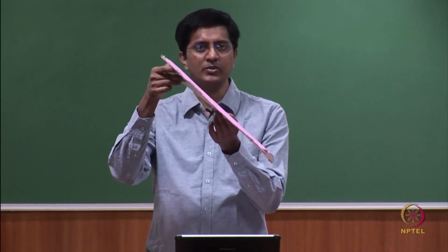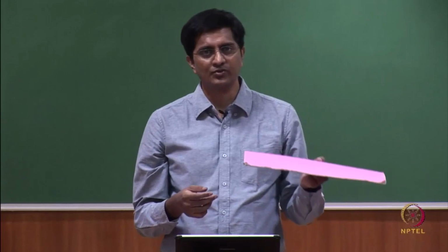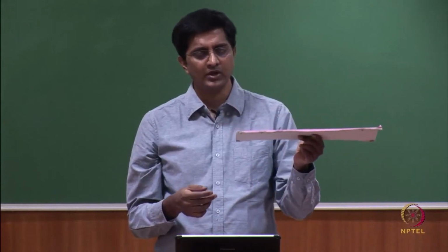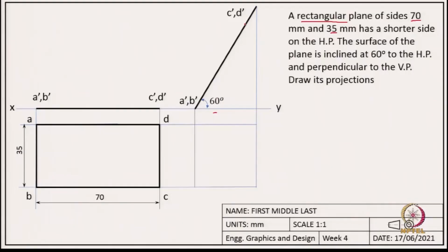In the second step, it is inclined. So, we use the information from top view of the first step and front view of the second step. So, once we get these two projections, now we can easily draw the top view. So, because these projections help us, especially these projections help us to determine what is the width when looking from the top view.